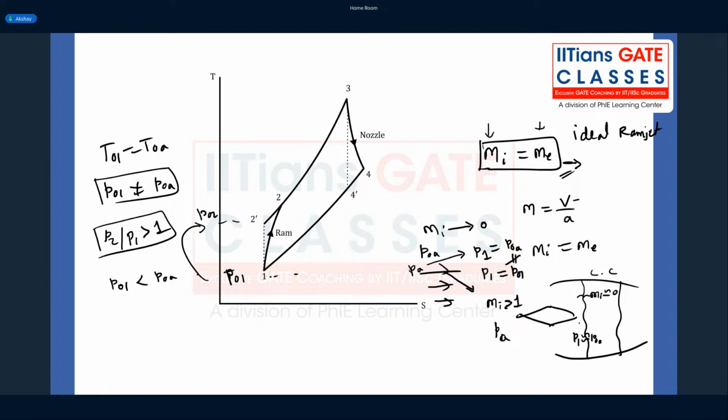So you increase the pressure and decrease the velocity, and now you are adding the energy in the combustion chamber. The fuel burns, the energy will be added to the system, so that the T naught 1 what you had here will be increased to a new value T naught 2. So now this is at a higher energy level because you have added the fuel, you have added energy. So this energy is now expanding in the nozzle, where again the reverse process happens. Here the flow has decreased, here the flow will increase.